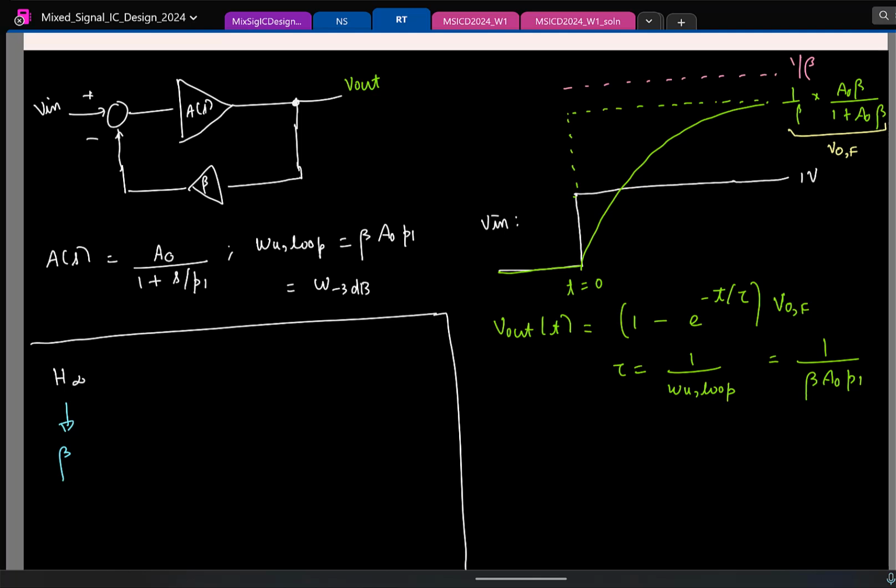Now of course, you can also be specified as to till what frequency you want the ideal closed loop gain, and that frequency is what? Yeah, basically that's the 3 dB bandwidth for the closed loop system, right? So you can have a specification saying my closed loop gain should be H infinity till so much frequency. That's indirectly saying 3 dB bandwidth or the time constant, right? Either of them. And as you guys pointed, this gives us the unity loop gain frequency for the loop gain.